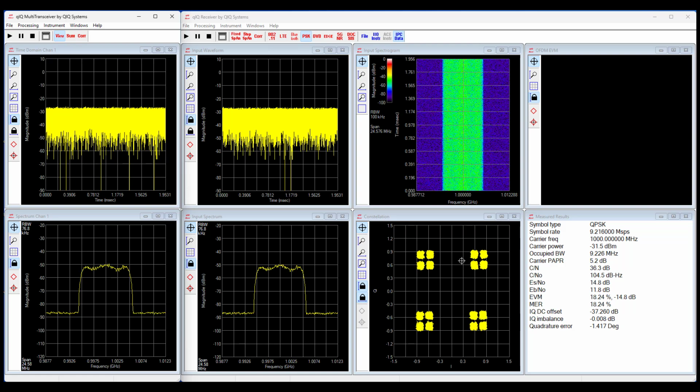That's what multipath is. Multipath is two copies of the same signal. One copy of the signal is generally attenuated and arrives later in time compared to the other one. So basically what you begin to see is QPSK on top of QPSK. It's just a strict superposition. You're just adding two QPSK signals together. And so you begin to see this QPSK on top of QPSK pattern in your final demod.